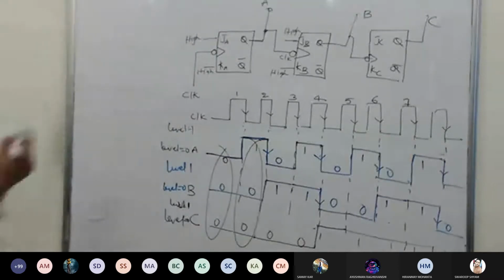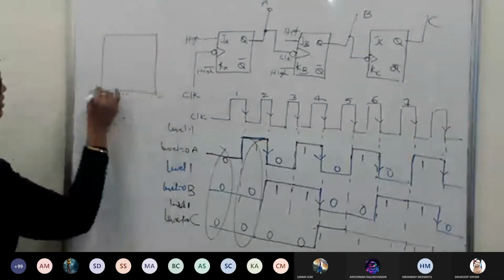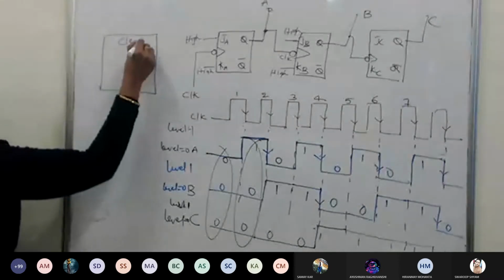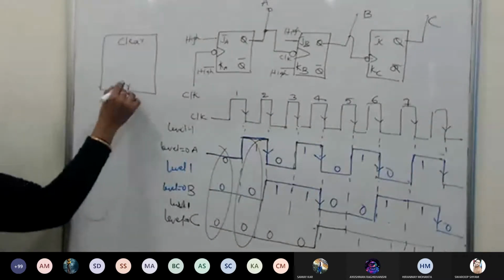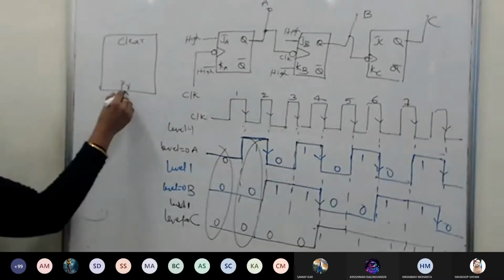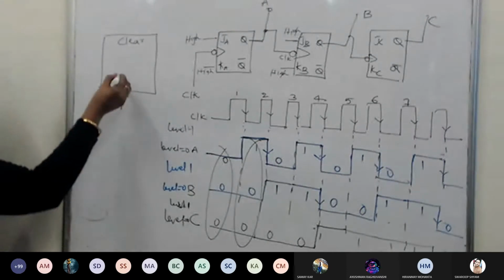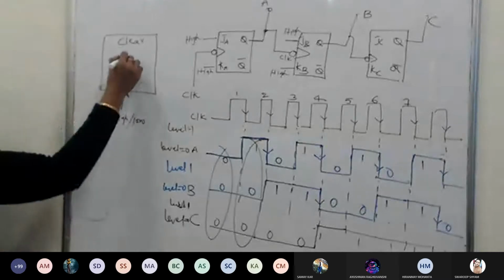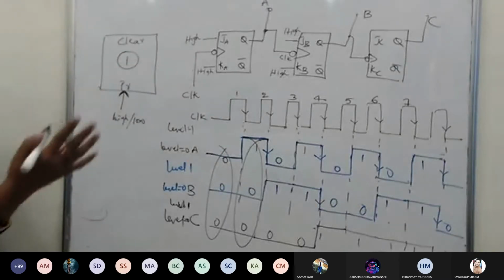So the flip flops, I am talking about the real design of a flip flop. What will happen? Actually, a flip flop will have two important pins. Earlier also I have told: clear and preset. Now preset, they will call it PR or PS. Whatever you send here, high or low, it will be retained in the flip flop. Consider it is T, JK or anything. So this is called preloading. You make it 0 or you make it high. So that was the starting point.